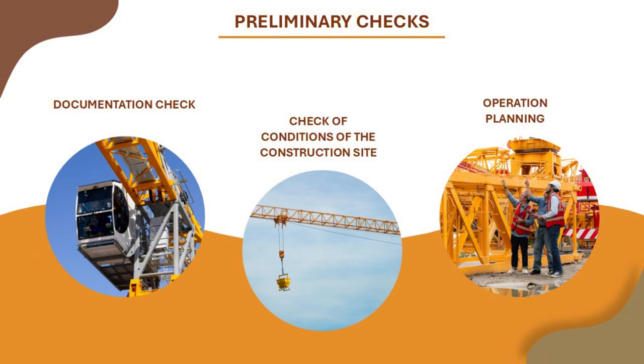Check of conditions of the construction site. Evaluate the supporting ground, which must be stable, level, and able to support the crane loads. Identify any interference, such as overhead power lines, other equipment, or nearby buildings.